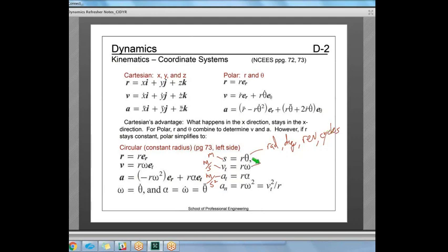How about omega? So omega is a rotational velocity. Instead of meters per second, we're going to have radians per second. And we could do degrees per hour or anything you can dream up could work in here. A very popular one is revolutions per minute, also known as RPM. So when you see RPM, I want you to think omega. It's a very common measurement of rotational velocity, right? Pretty much every time you're presented with an RPM, you're going to convert it to a radian per second sort of thing.